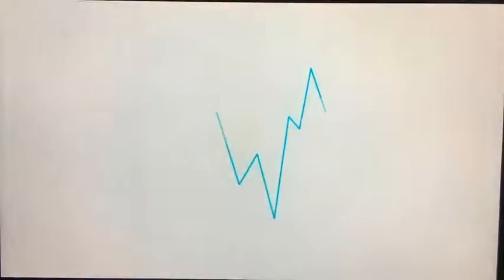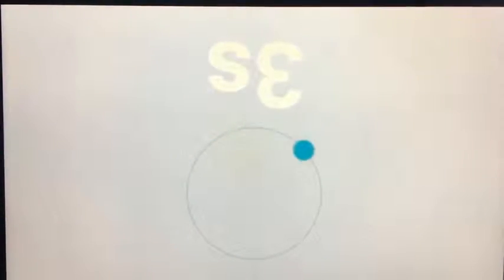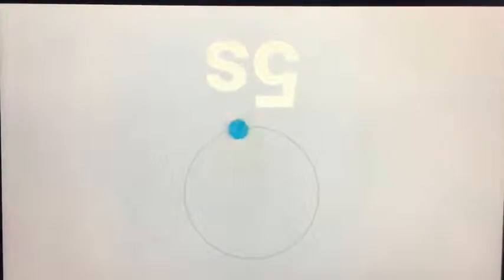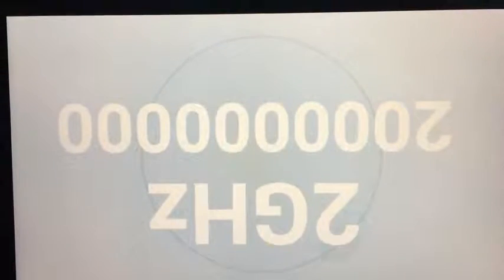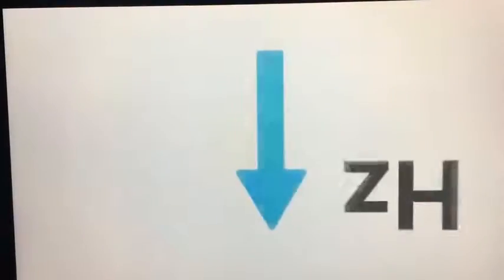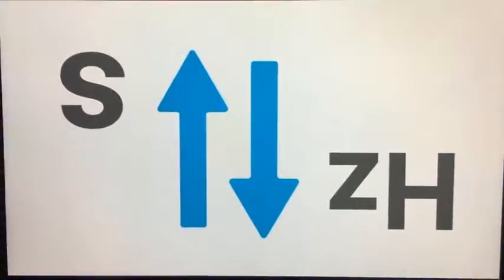The clock. The clock is responsible for defining the frequency that your processor will use to execute one task. It's measured in hertz. This means the amount of cycles that can happen in a given amount of time, in this case, in seconds. For example, if a processor has a 2 GHz clock, it can have up to 2 billion cycles per second. So the higher your clock frequency is, the lower the execution time will be, which for you means a faster processor.